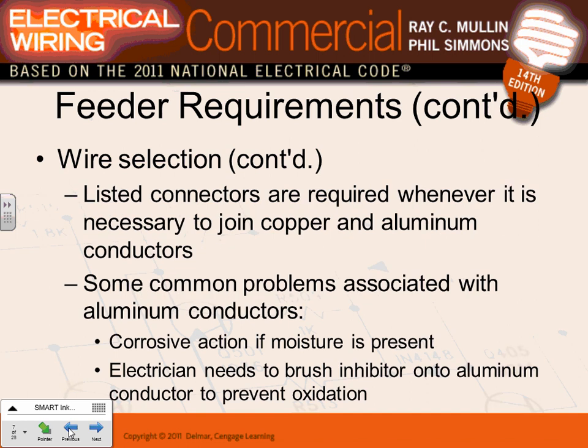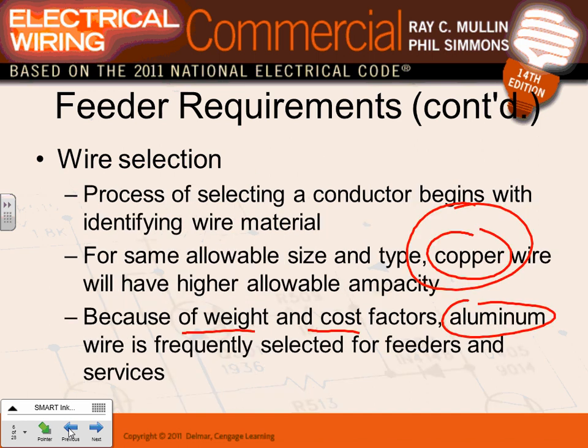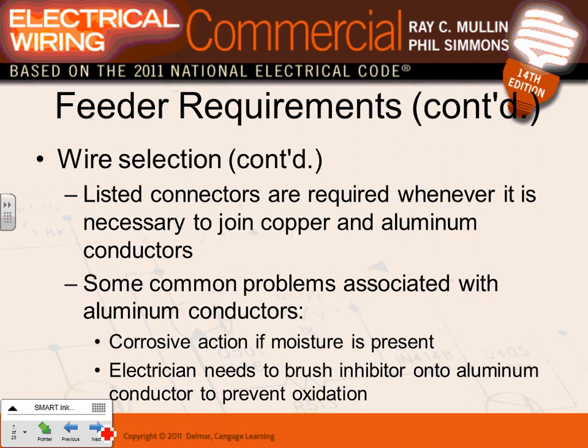The other thing is that aluminum is a big deal, guys, if weight is an issue. If you want to hang these cables from a structure and you're not really sure about the weight it can take, you don't want it to collapse. So copper would be highly unlikely there, but aluminum would be an option for you.